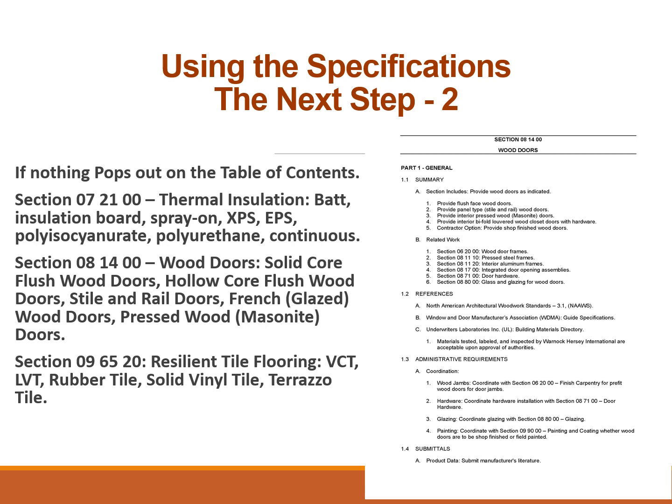Now, that tells you that we're not assuming these wood doors are going to come out to the job site with glazing in them. We're assuming they're going to come out to the job site, whether pre-finished or shop or field finished, but they are going to be glazed in the field. So this is a continuing way to learn how to read the specifications by looking for keywords and knowing where you find the primary areas that tell you where things are at.